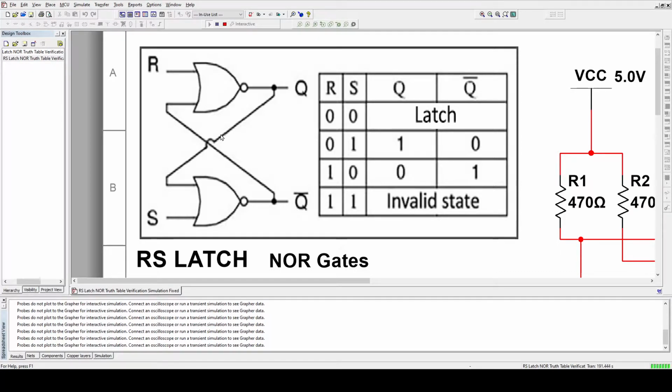Right. Now when we talked about the multivibrators, which kind of multivibrator would this be? Is it a monostable, is it astable, or is it bistable device? Well, basically what we can say is that it has two valid states. The output can either be here, that stick can swivel from the middle to here, or it can go here. It's just like the stick was swiveling from Q to not Q.